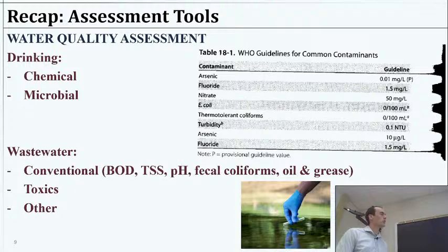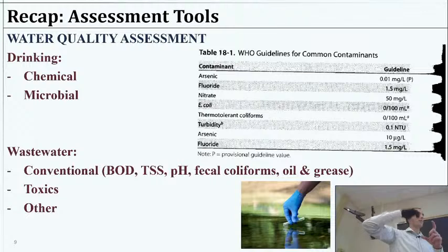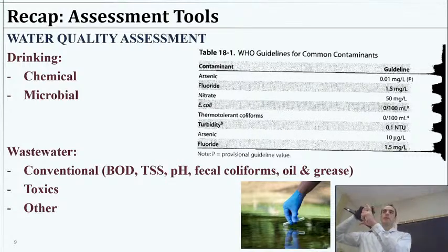Okay, so those are the major types of stuff we would get into, how to measure things. There are more ways and more tools out there. I didn't really mention chlorine testing. It's going to be another colorimetric thing. There's a few neat ways to do that. Kind of like the pH strips, you can get the chlorine measurements to have a dial that says, okay, this amount of pink from this particular method relates to about 1.8 milligrams per liter of free chlorine, stuff like that. Last year when I went to Nicaragua, we were using one of those and it was working pretty well.